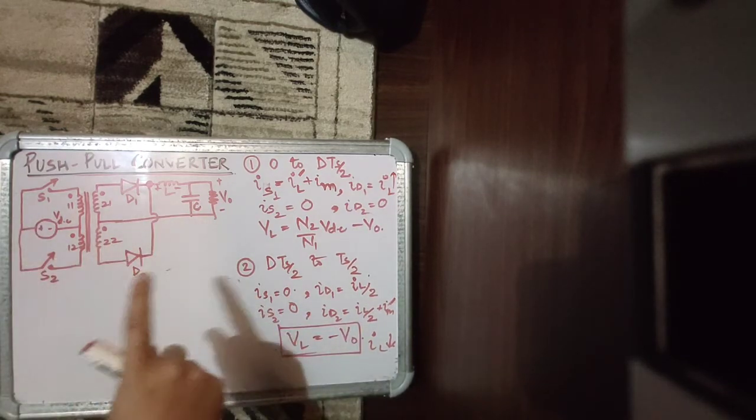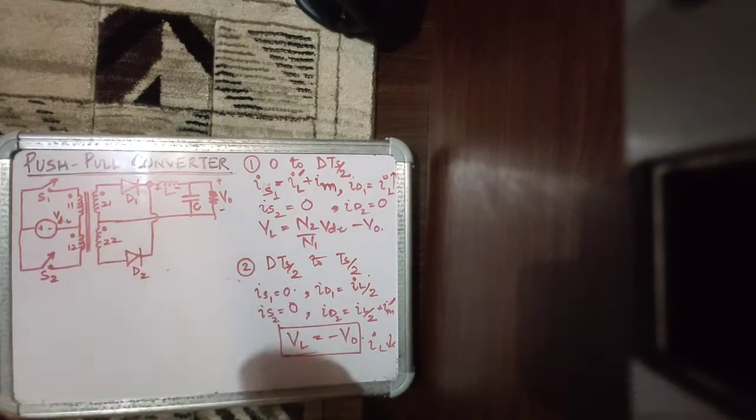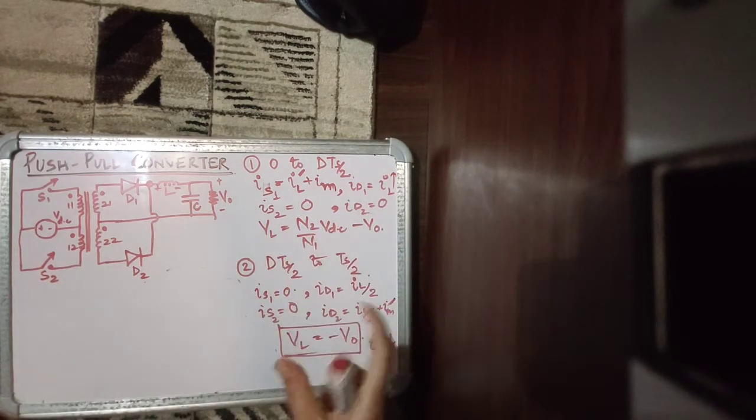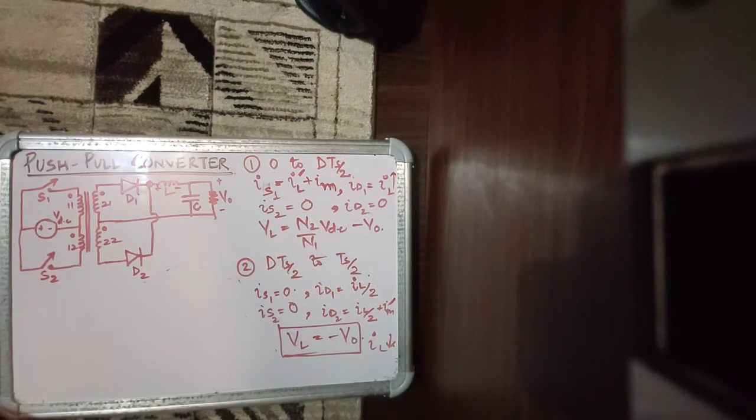अब जो S1 से हो रहा था और D1 D2 से हो रहा था, अब सेम चीज़ रिपीट होगी, लेकिन अब वो S2 से होगी, दूसरी डायरेक्शन में फ्लक्स बिल्डअप होगा और दूसरी डायरेक्शन में कोर एक्साइटेशन होगी. But the circuit behavior will be symmetrical now, it will repeat. So हम इन दोनों के लिए ही, if we do the analysis, that is sufficient.